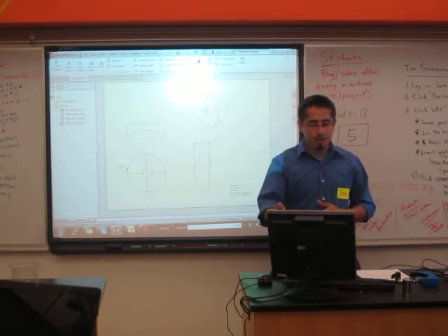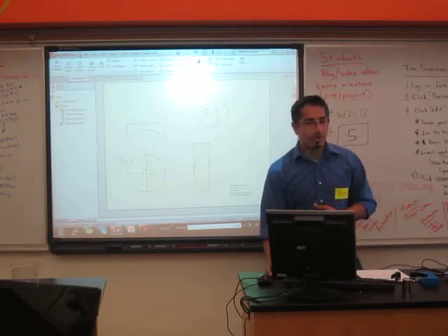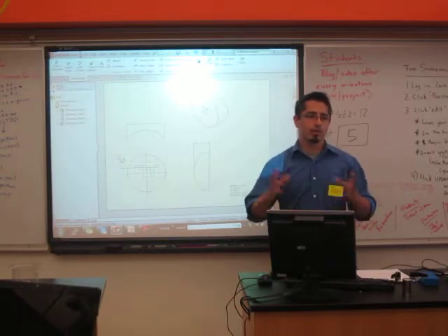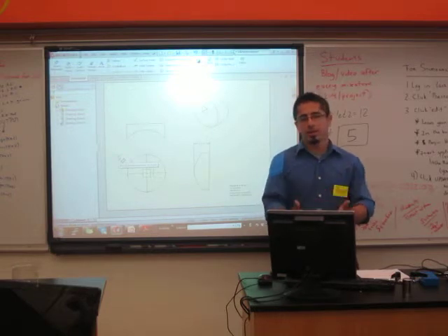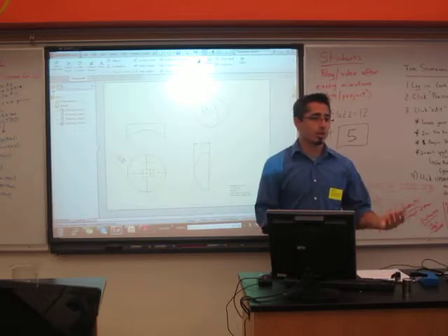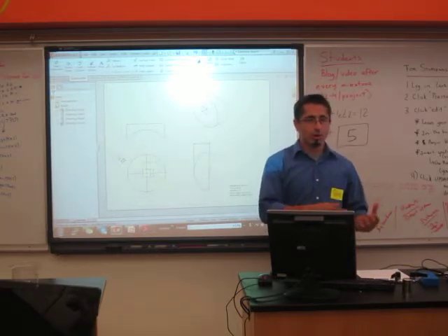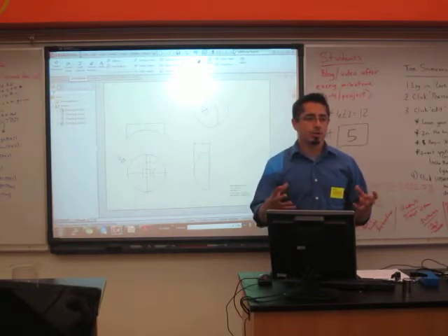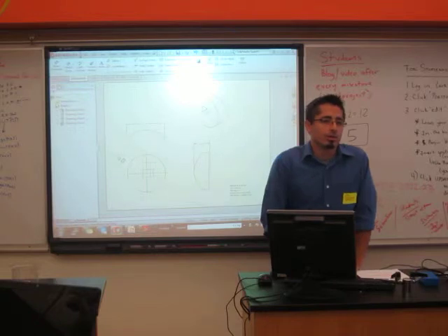I don't know how accurate that's supposed to be. By putting it into a blueprint, I can then say this 2.50 is going to have a 20th thou accuracy, or a 16th of an inch accuracy, or an 1/8 of an inch accuracy. I don't really care. It could be an inch bigger. It doesn't matter to me. So by putting that in the blueprint, you then specify that. Ideally, you work off the 3D model, especially when you're machining it. You just toss it into their software. They machine it straight off your model, and it comes out as close as theoretically possible. But materials in reality don't come out that way.